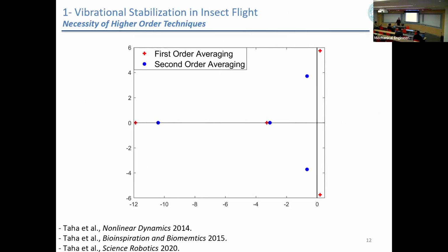They are zero mean, perfectly zero mean. And they are very high frequency, 30 times the natural frequency. So it's quite legitimate, it's intuitive to think they do not provide a significant contribution. Yet they shifted all the poles, all the eigenvalues, to the left half plane. So on the average, the system is unstable, but these high frequency vibrations of zero mean induce a stabilizing mechanism.